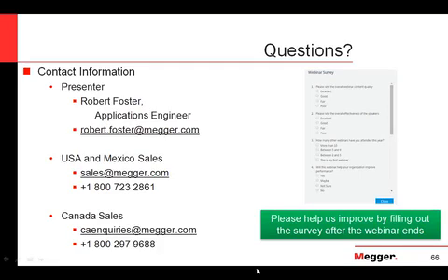Okay. Robert, Gary asked that many manufacturers claim that it is not necessary to test motion in a vacuum circuit breaker. In your experience, is this true? What I've seen with the vacuum circuit breaker is at the factory, they're measuring motion for sure because they want to look, a lot of times, for that rebound parameter where the contacts touch and it backs off. From a field perspective, I would say less people are doing the travel.